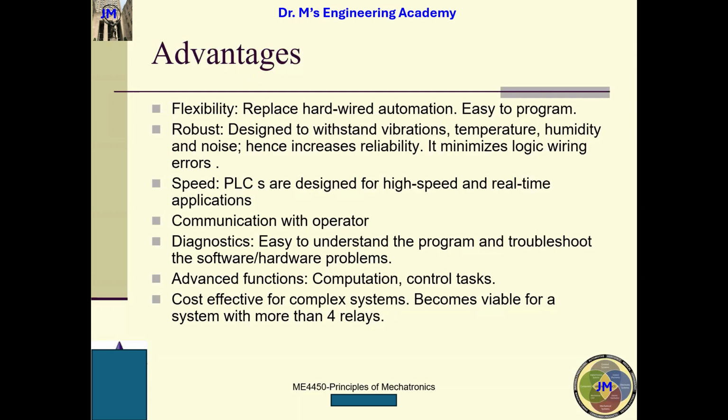It is cost effective for a complex system. The more complex a system you have, the better it is for you to use a PLC. It's worthwhile to spend thousands of dollars more to buy a PLC instead of using many control relays and a lot of wires for your system. If you do it that way, you will be very, very confused later.